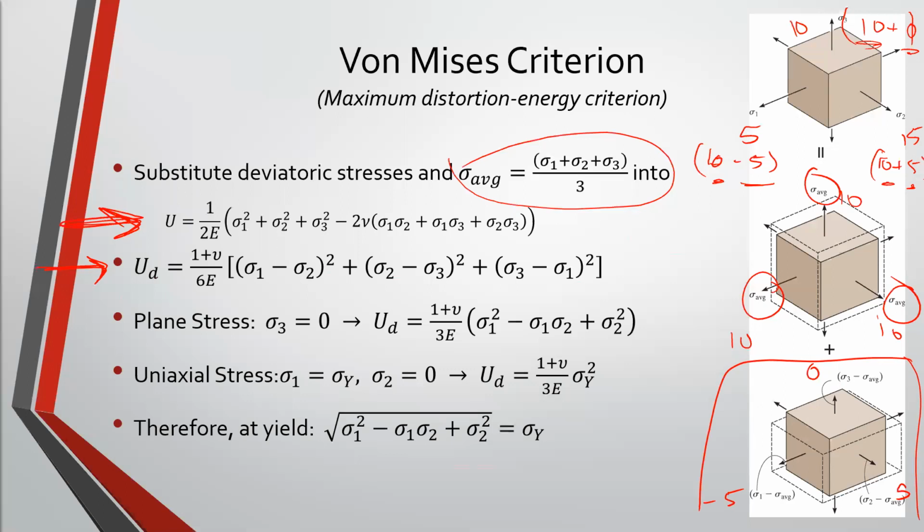So it's the difference between the y and the average? Yes. Now, if we want to be a little bit more technical, you said it's the difference between the applied stresses and the average stresses. That's true. Those average stresses have a very special name called hydrostatic pressure. It's where everything has the same stress on it. Every face has normal stress of the same magnitude.